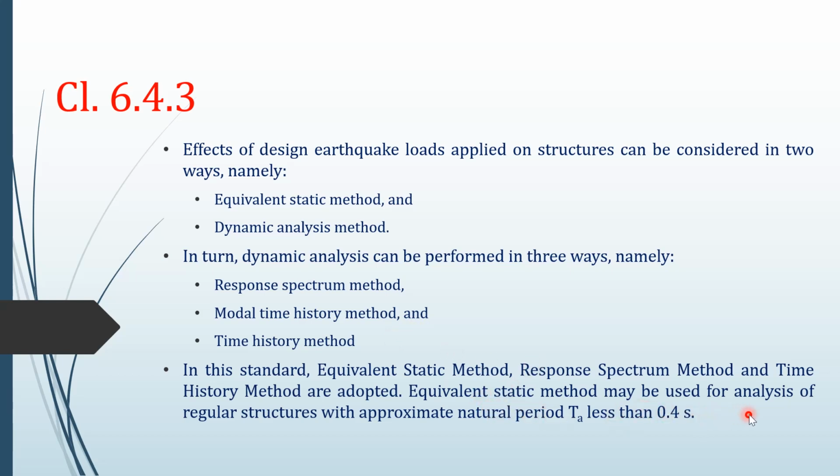Equivalent static method may be used for analysis of regular structures with approximate natural time period less than 0.4 seconds. That means only for regular buildings, buildings which are regular in plan and elevation, which do not have any kind of irregularity, including mass irregularity, stiffness irregularity, or any other torsional irregularity.